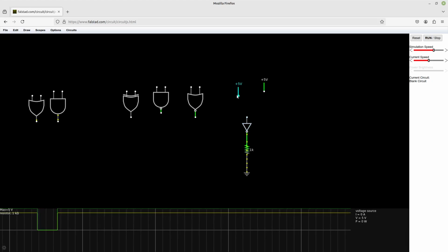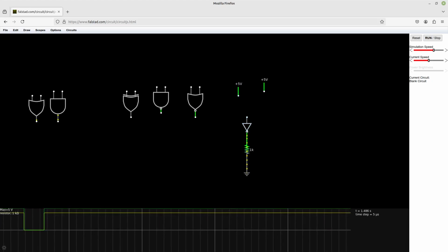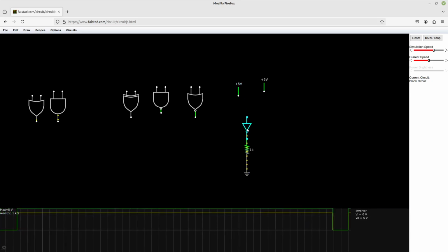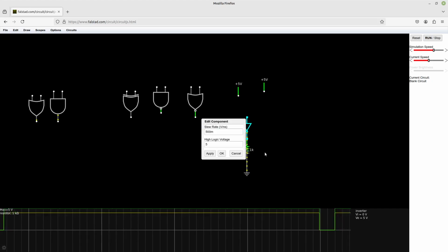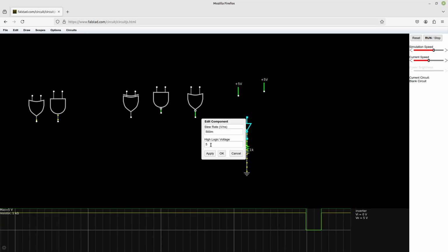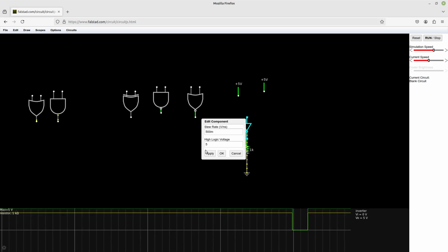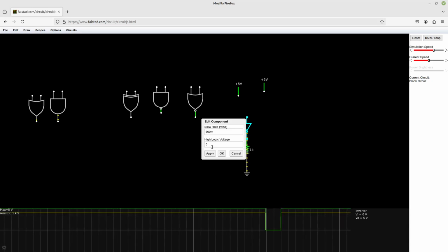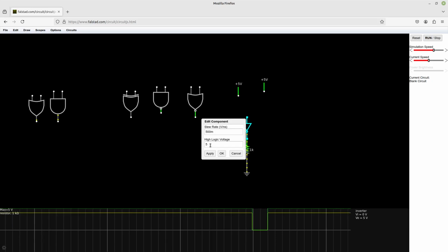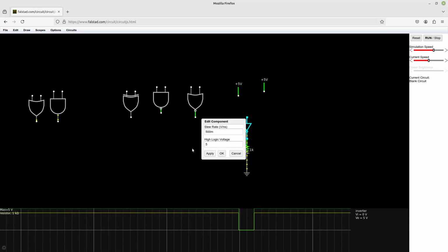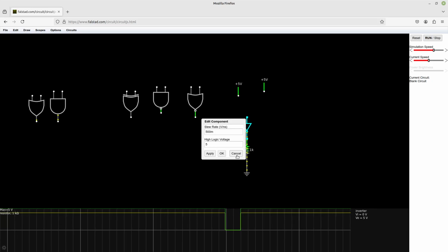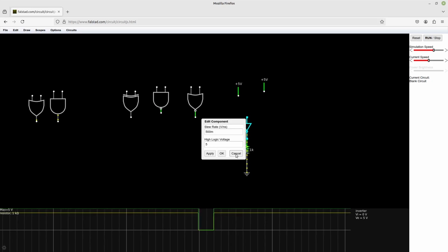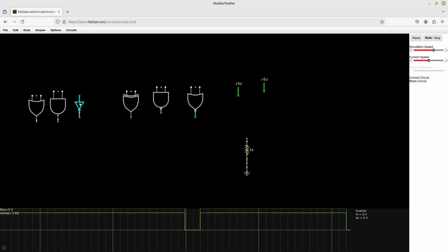So again, looking at this one, right now there is 5 volts coming out, and if I apply 5 volts, all of a sudden it will drop. Now if I go into the settings here, you can see that 5 volts is the logical high that it has, and we could change this to 10 or 9 or 3.3 or whatever for the simulator here, depending on what voltages you're actually expecting to work with if you were making a chip per se. All right, so that's the NOT.